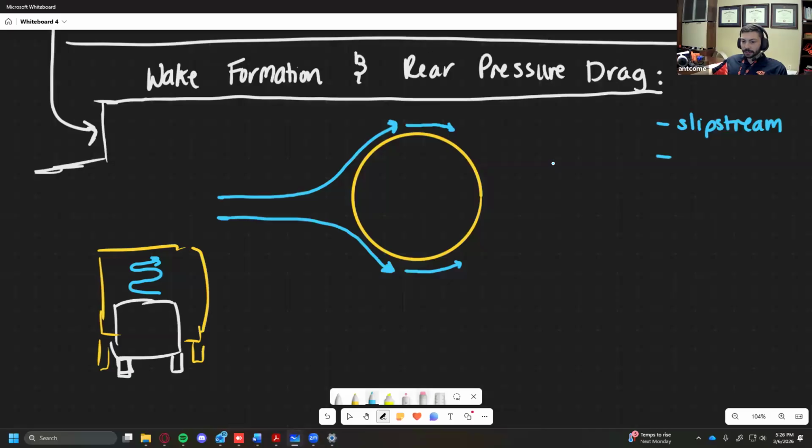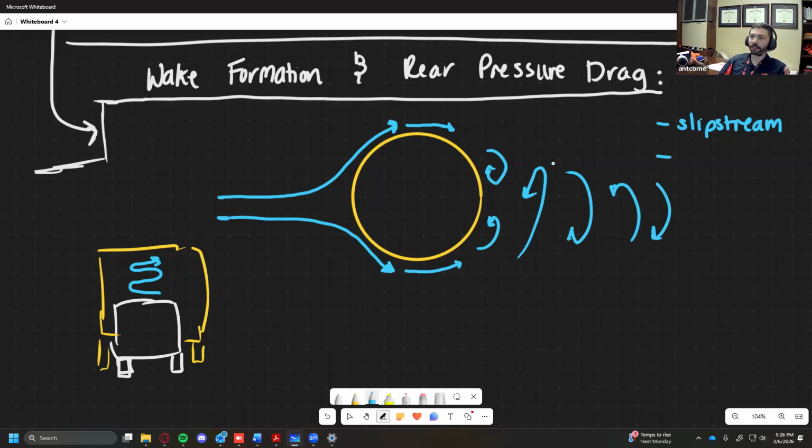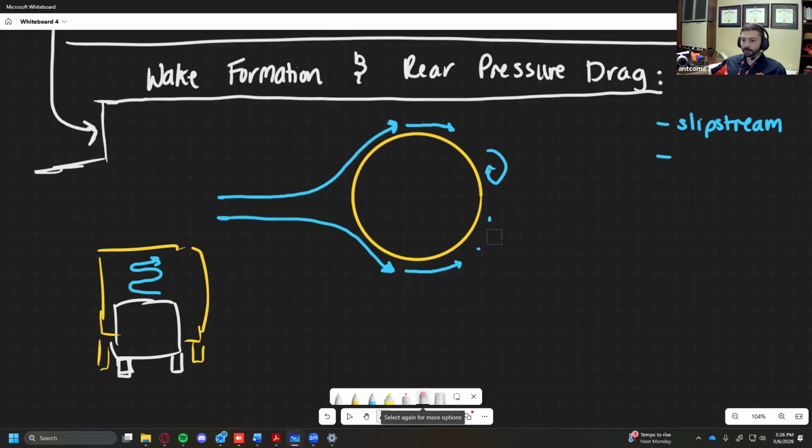I'm curious. So this effect that you see is due to something called von Karman vortex wake, and it ends up having wakes that do this and this and this and this, and your car gets hit left and right and left and right. And some trucks that you'll see on the road actually have on the back of the truck, so if the white part is the truck trail bed, they will have this little thing.